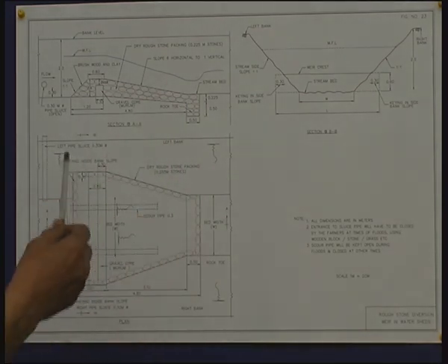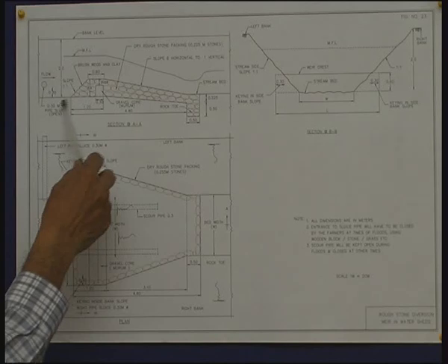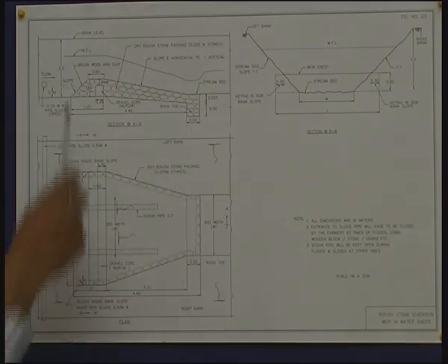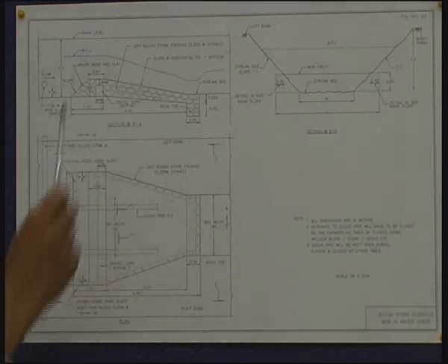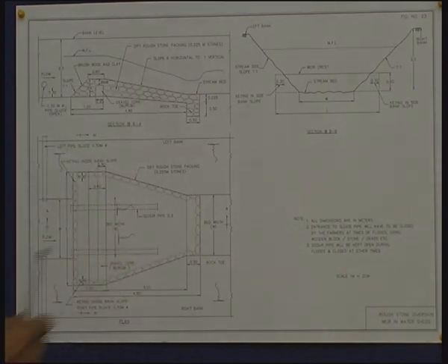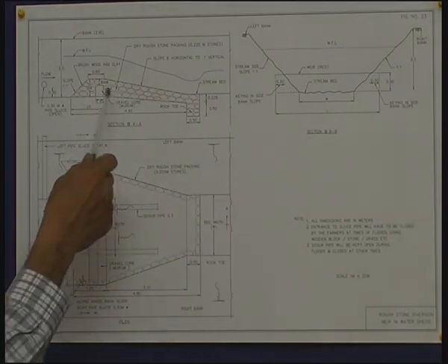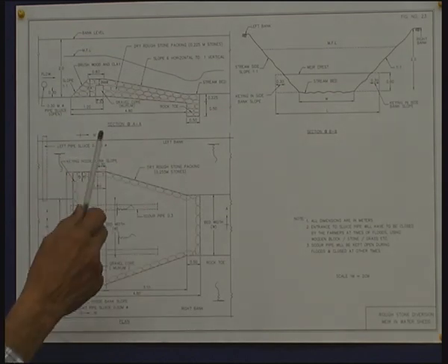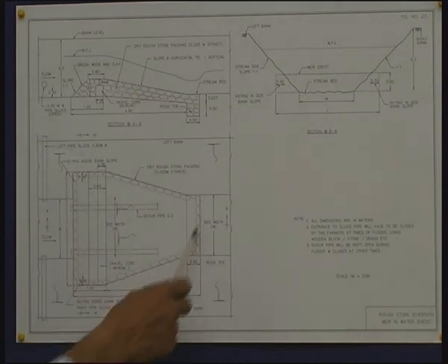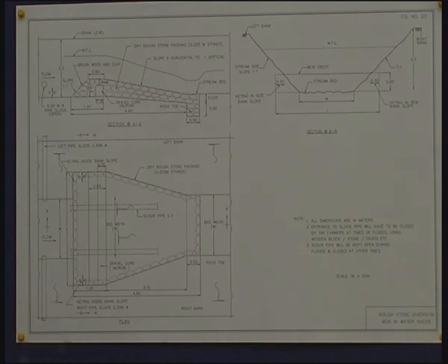As an addition to the tribal technology, if this is done, then such a structure would be stable even under the maximum flow conditions. It will not get breached. For any reason of downstream scour at a later date, if any damage occurs to the structure, this can easily be repaired by the farmers. The total cost of the entire thing is only 4,000 rupees, and the repair cost would be within their means. So, by means of such a simple structure across the main stream, it is possible to irrigate lands by gravity flow canal without even resorting to pumping.